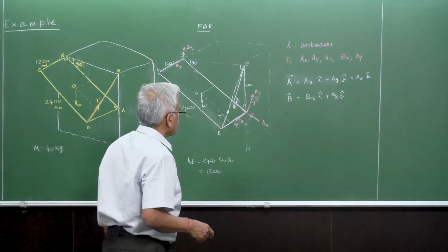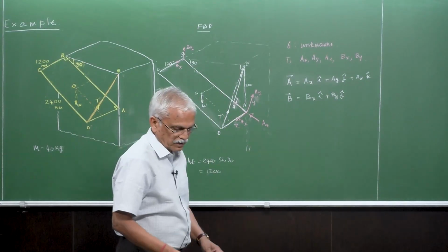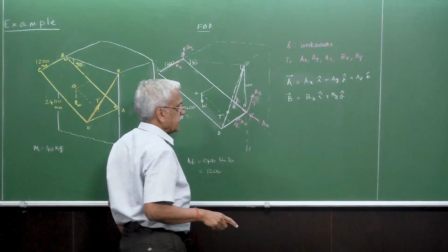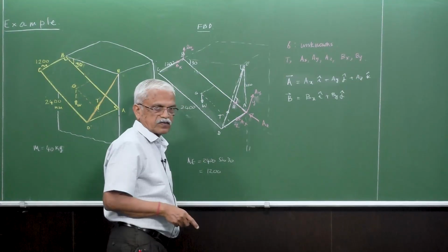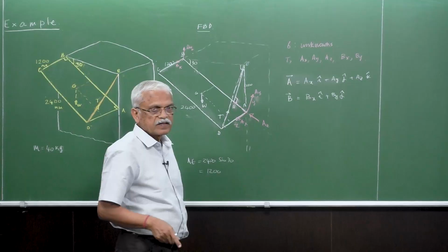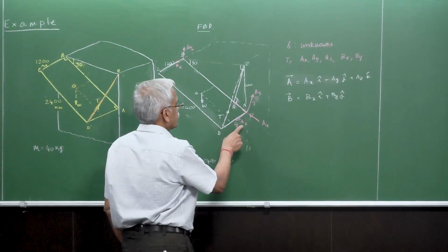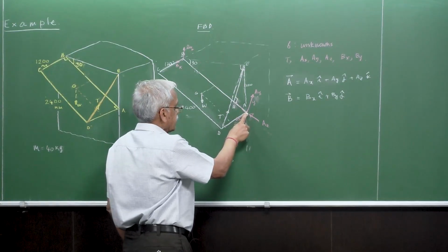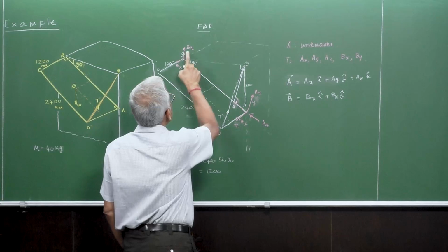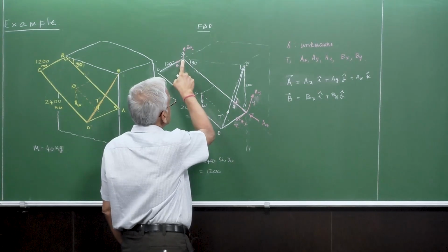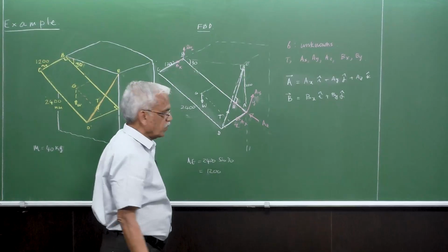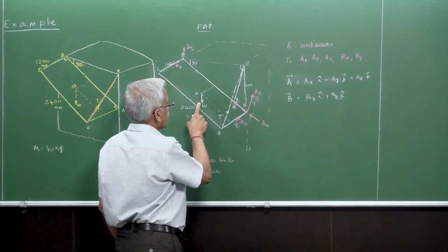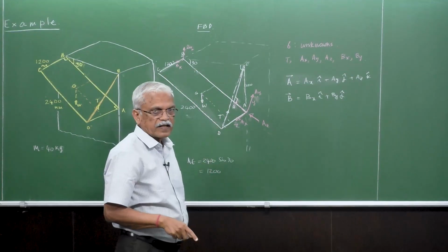Why we take the moments is that if we want to take the moment about A of all the forces, you can see immediately the advantage that all the forces Ax, Ay and Az about point A are 0, and many of these things, Bx, By, their moments about A can also be 0, leaving only the moment of T about A as well as the weight about A.